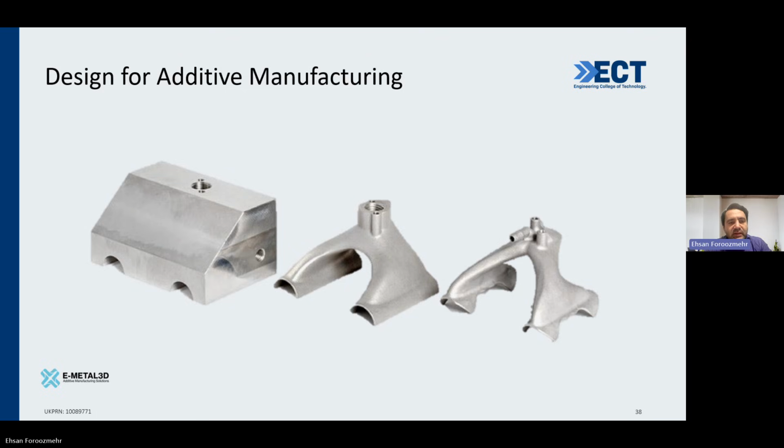If actually the client brings this left part and tells us, okay, I want to do 3D printing on that, we say it doesn't work. It doesn't mean that 3D printing cannot make that, but it means the 3D printing of this part is going to be very expensive, because you have to print a lot of material that are practically useless. That is why the printing of the left part is going to be very expensive.